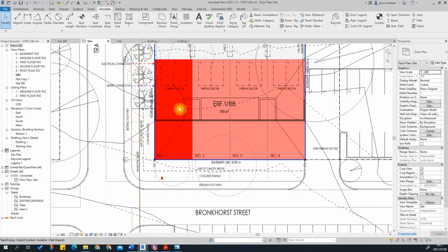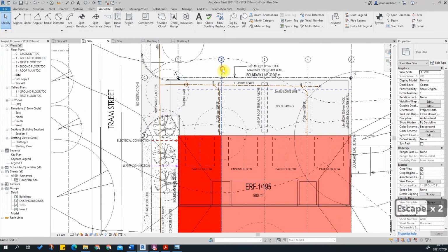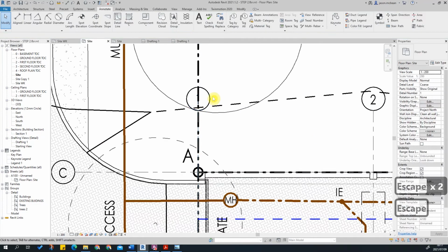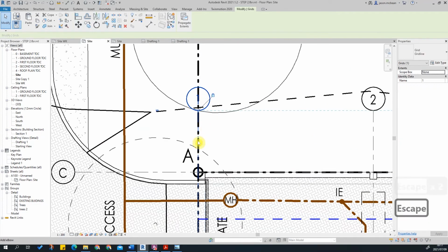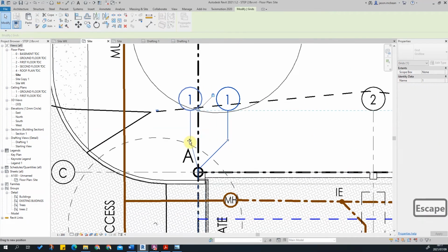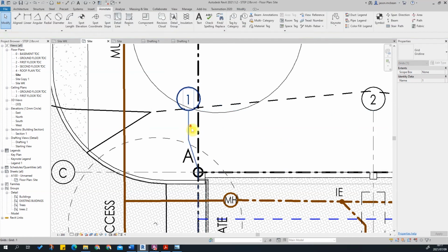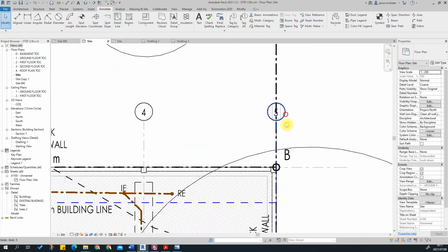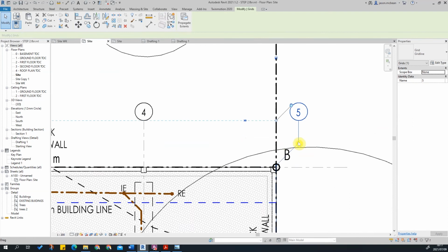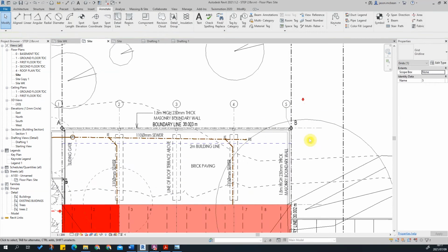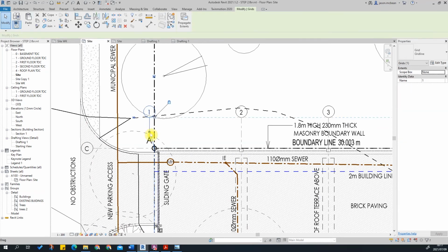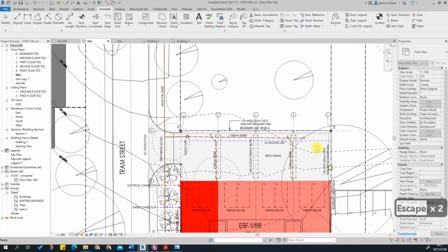The last thing I need to address now is to fix my grids. When you have a grid in this situation where it sits on the edge here, you've got a break line tool that you can use to break the grid away so that it's legible. That's what you need to do with these very quickly, because you don't want it sitting over that thick line work. You can take it in or out, that's totally up to you. Let's do the same this side, so we're keeping things consistent.